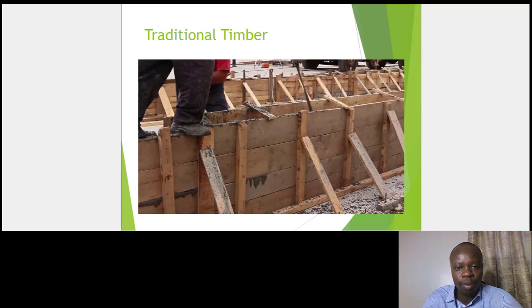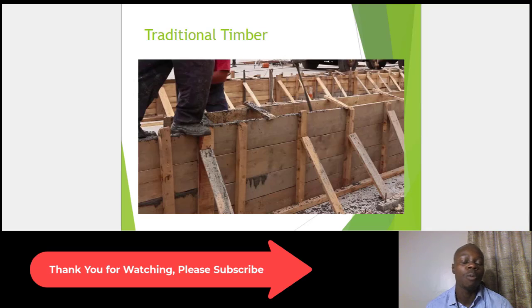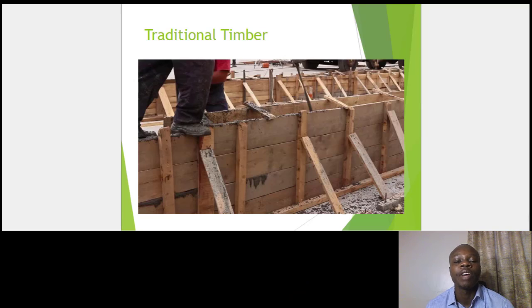The formwork is used to contain the concrete into the shape and size that has been designed, and also to allow it to gain sufficient strength before it can be left on its own to support its own weight. Therefore, as a quantity surveyor, it's important that you know how exactly to measure formwork, because it's a cost item and it's going to affect the overall cost of construction at the end of the day.